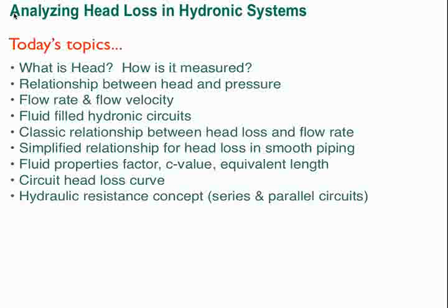We're also going to draw an analogy between electrical circuits and hydraulic circuits or hydronic circuits. The concept of resistance. If you've worked with electricity, I'm sure you know Ohm's law, and you know that you have resistances in electrical circuits. Those resistances can be combined. Sometimes they're in series. Other times they're in parallel. But we're going to draw an analogy to that with a hydronic circuit. It's a very powerful way to look at hydronic circuits, and it's a way to analyze those circuits.